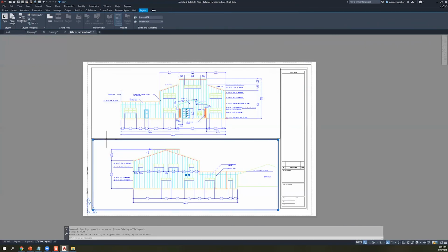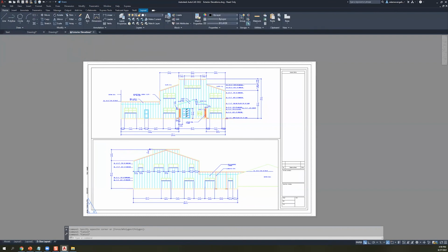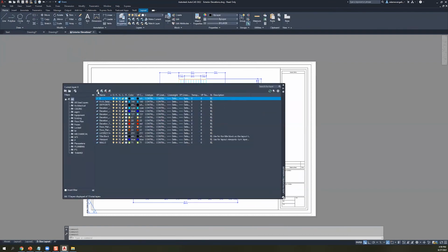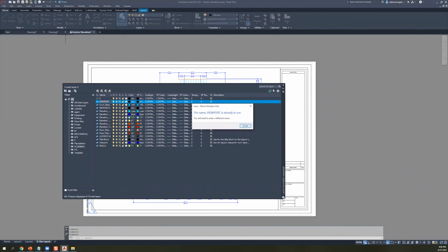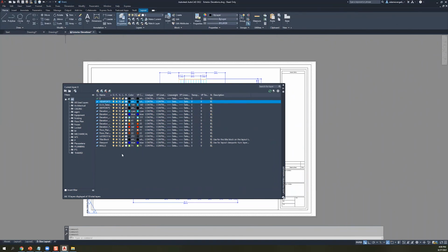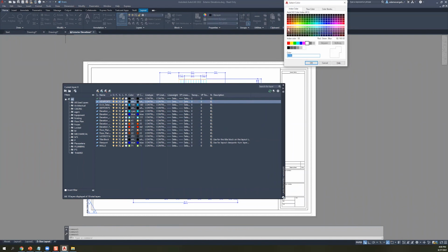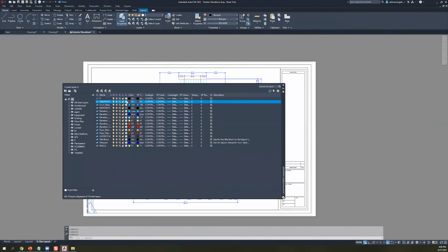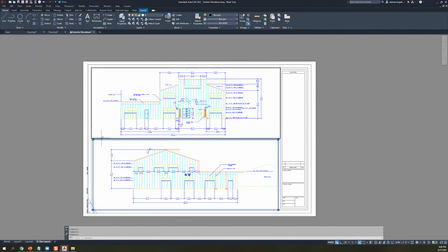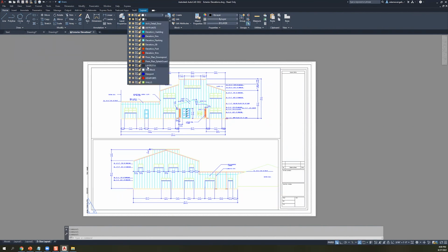And the way to get rid of those lines on your plot is to create a new layer in particular. So I'm going to go over to Home, do a layer over here. And there is a viewport layer here already. I'm just going to make a new one so you guys can see it, right? So viewports, plural. And the main thing I'm going to do here is I could even call it a different color just for the sake of visibility, I guess. There we go. And I'm actually going to toggle off the plot option over here. So anything on this layer is not going to plot, which sounds a bit counterintuitive given what we're about to do over here. But now I'm going to select these two objects and move them to my viewports layer.